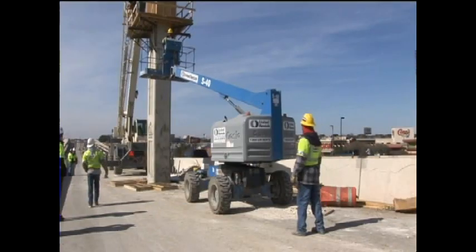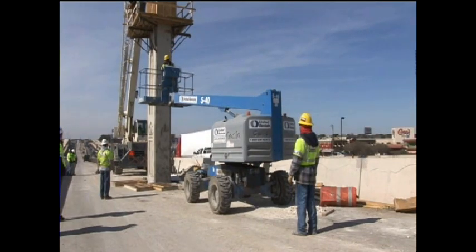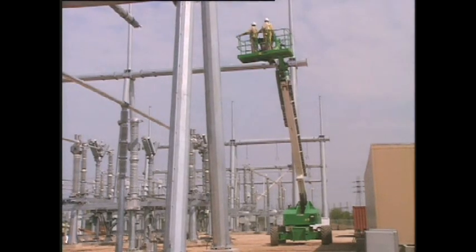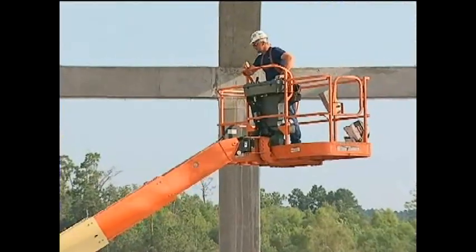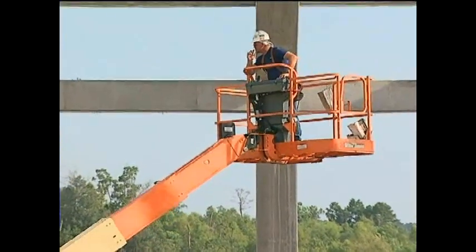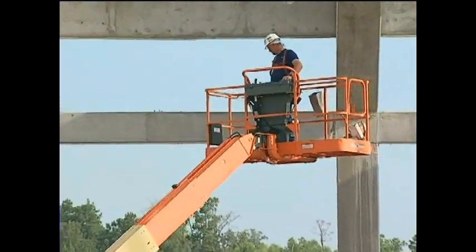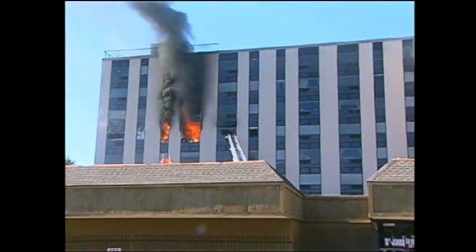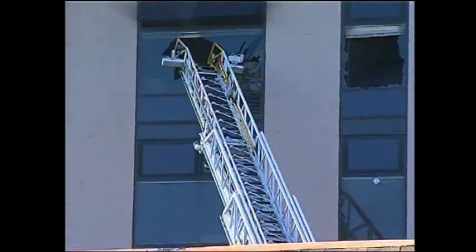Aerial lifts include several types of vehicle-mounted aerial devices used to elevate employees to job sites above ground. An extensible boom platform uses a single arm to lift a platform to the desired height, often by hydraulics or, less frequently, pneumatic pressure. The length of the arm limits the reach of the boom lift. Some boom lifts can extend the reach by using telescoping sections within the arm. An aerial ladder is an aerial device consisting of a single or multiple section extensible ladder. These ladders are those most often used by fire departments.